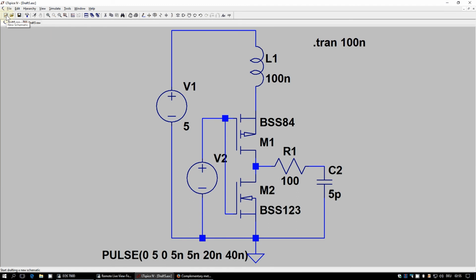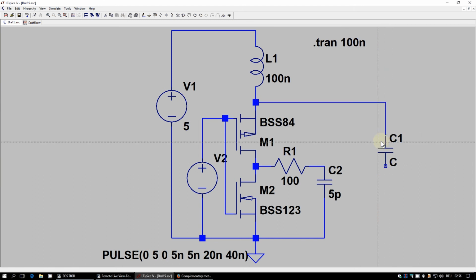So the simple remedy for this is, of course, inserting a bypass capacitor of traditionally 100 nanofarads with every IC, and perhaps every 4th or 5th IC in a row you put a tantalum or aluminium electrolytic of, let's say, 10 microfarads, but we'll only take a look at this directly with the shortest possible leads.